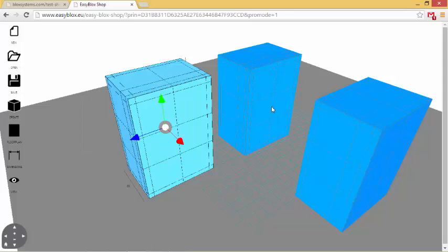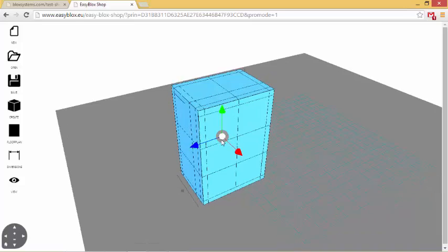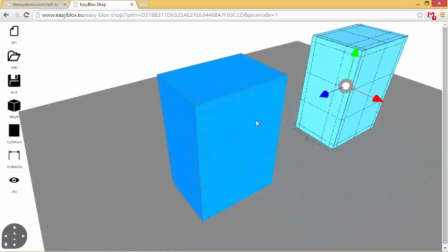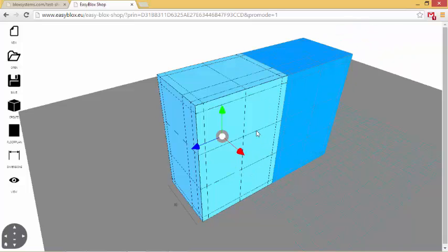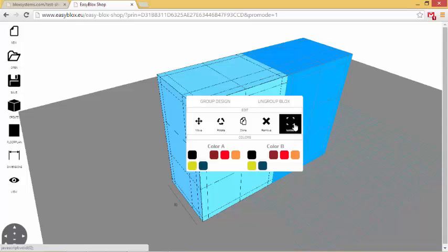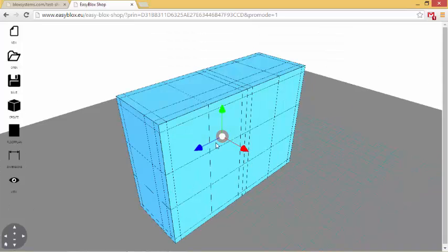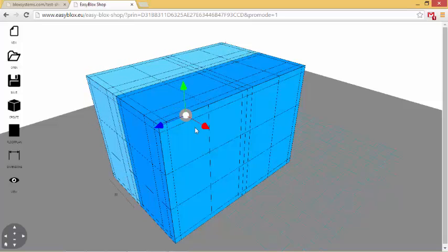So what this means is, for instance, in the right click menu, you have different products in your scene. Imagine you have a reception and you only want to edit this one. Then you can click isolate. Isolate will hide everything else out of the scene. So for instance, I'm holding Shift now to copy.